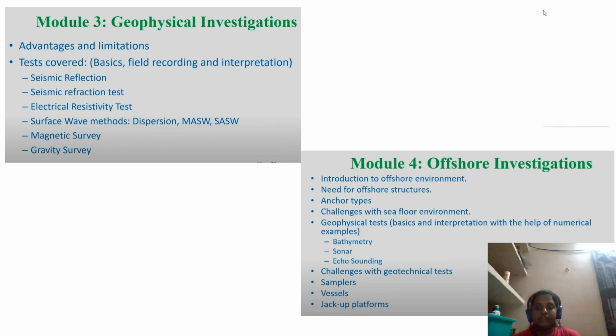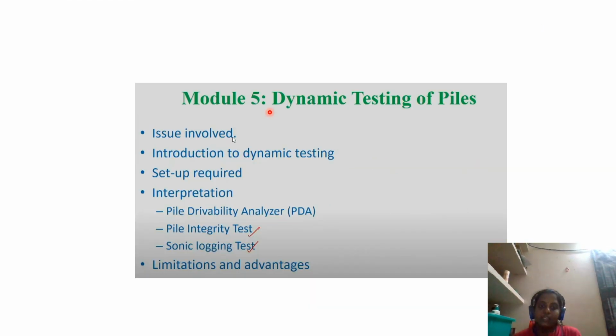Then module 4 is about offshore investigation, and how to collect samples offshore. We saw some very basics of different types of anchors, how offshore profiling is done by bathymetry survey, sonar, and echo sounding, how they collect samples, and the various components of a vessel. Then in our last module, module 5, we saw dynamic testing of piles.